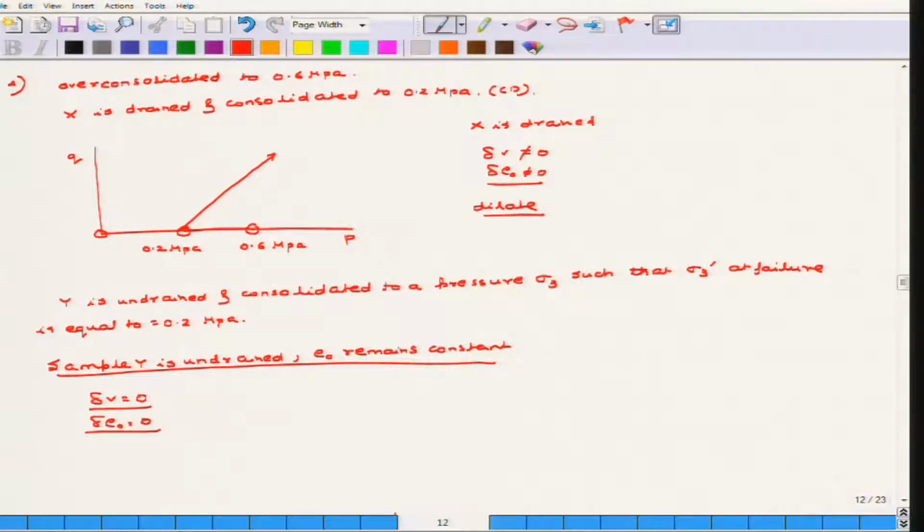So in this problem we have discussed how, with the help of stress paths, or by applying basic concepts of soil mechanics, you can think about what the shear strength should be when you are comparing two samples, whether in a consolidated undrained test or a consolidated drained test it should be greater or less. Like I have said previously, with the increase in strain rate, especially in case of a consolidated drained test, it will behave more like an undrained manner. So in this case, the strength is going to decrease or increase depending on whether the clay is normally consolidated or over consolidated.